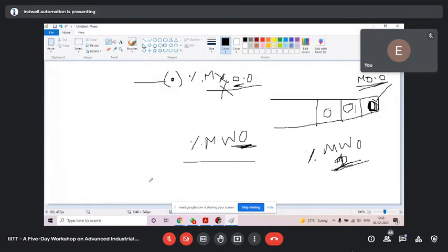So as you press the start button, you remember the timer program. I0, Q0 on for 10 seconds. You press I0, you take the M0 latch. From M0, you are running output Q0. From M0, you are taking a timer, and for that timer visualization you have taken %MW0, suppose, time to word.